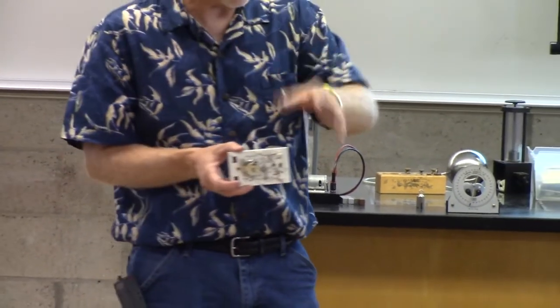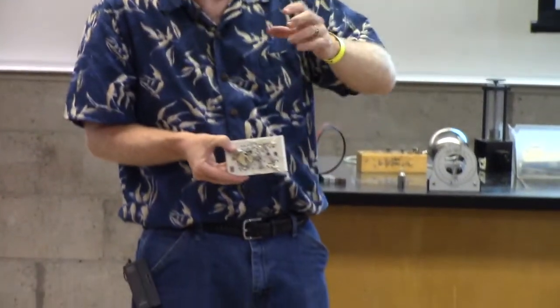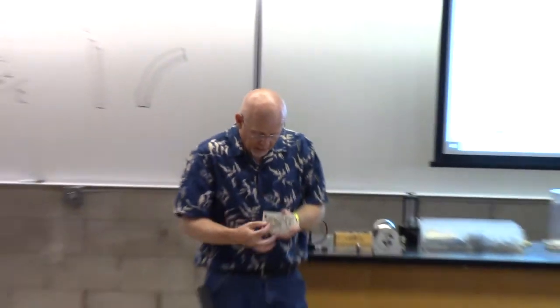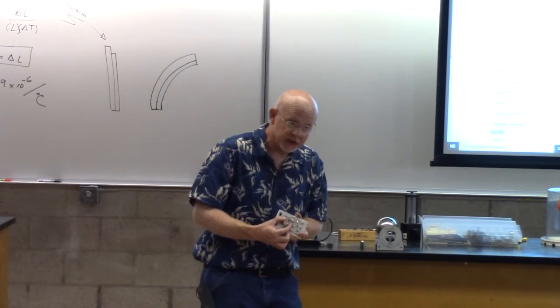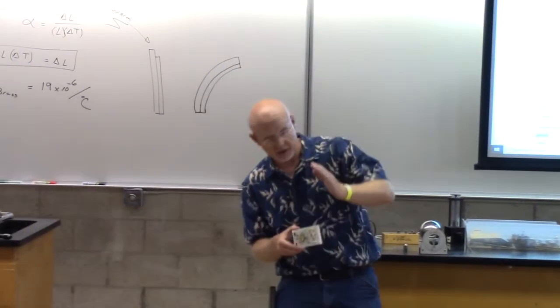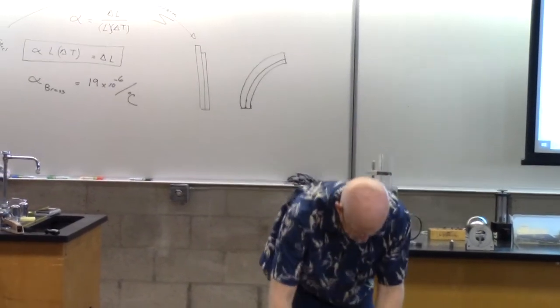And so if it gets under 65, furnace goes on. Furnace starts to warm up the house. As the house starts to warm, the thermal expansion moves the bimetal strip and then eventually turns off the furnace. And so there's this constant on and off to the furnace using the bimetal strip.